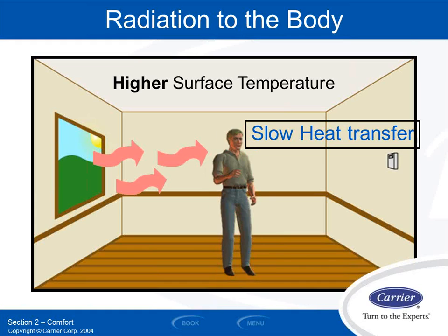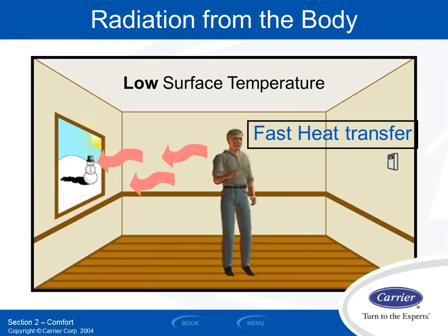So let's say it's a 100-degree day out. So the inside surface of my glass is like 95 degrees or something like that. So that 95-degree glass is shining infrared heat to my body because my body is only 92, 93 surface temperature, right? So the higher temperature object shines infrared invisible heat to the cooler object, right? In most spaces, it's the human that's the hotter object in an indoor space, but there are scenarios where that's not the case and the object is warmer.